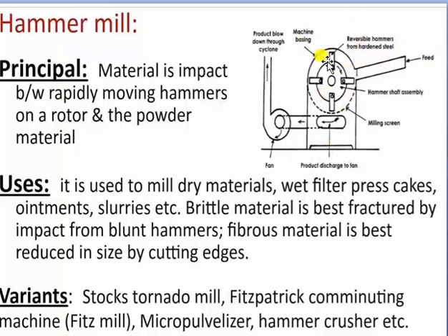It is connected with a motor. While the machine is on, these hammers will rotate, and due to the impact force, your material will break down, and then one screen is attached here. That limited size particle will be collected. Here is your discharge pan. Here you can discharge your samples.